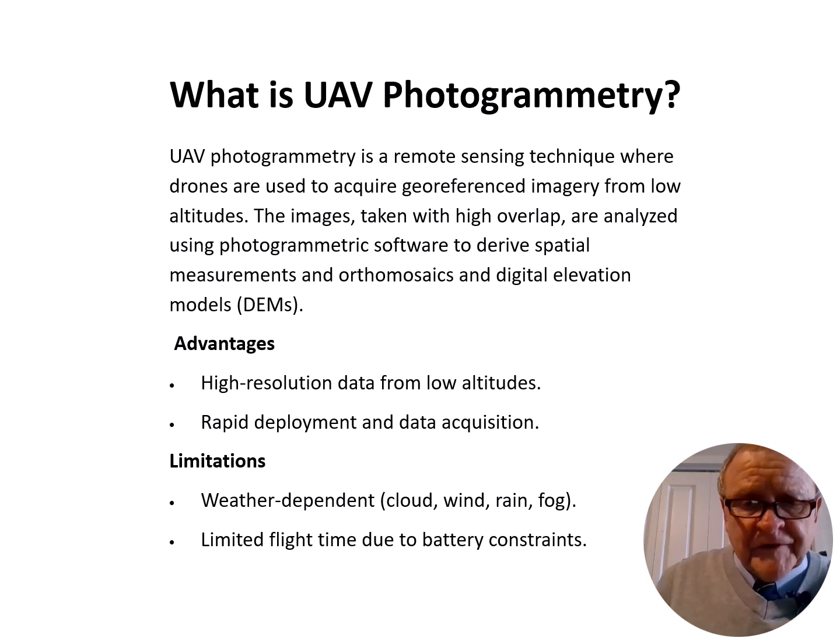What is UAV photogrammetry? UAV photogrammetry is a remote sensing technique where drones are used to acquire georeferenced imagery from low altitudes. The images, taken with high overlap, are analyzed using photogrammetric software to derive spatial measurements, orthomosaics, and digital elevation models, DEMs.